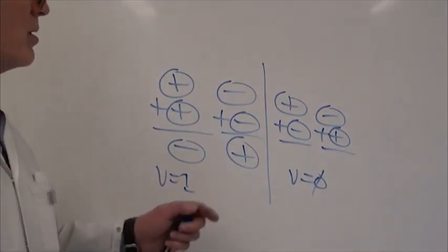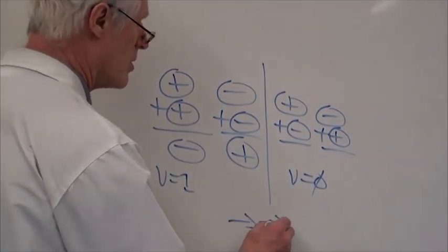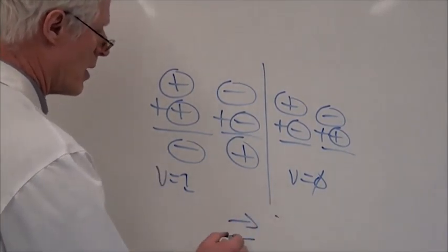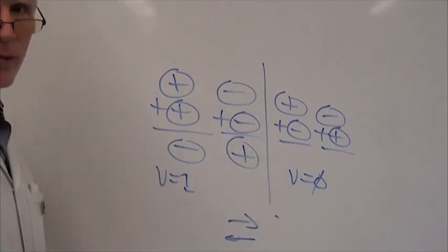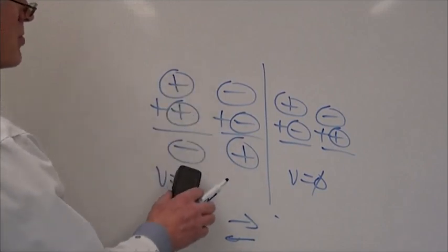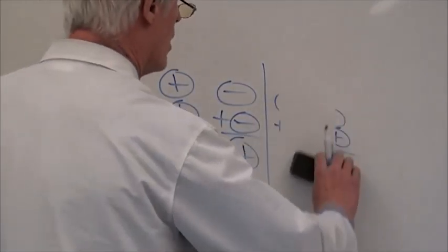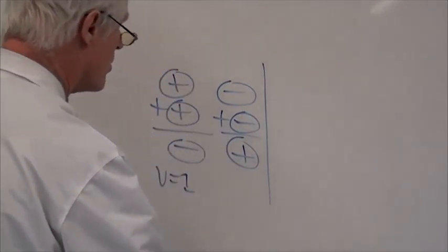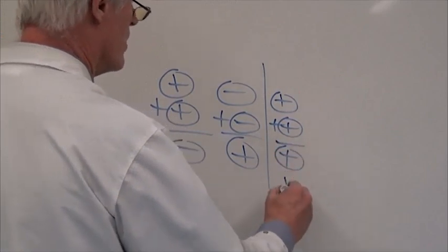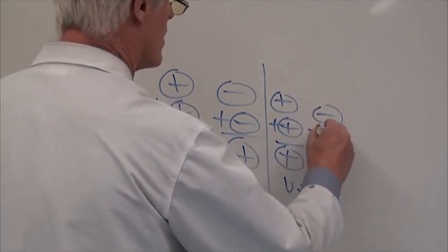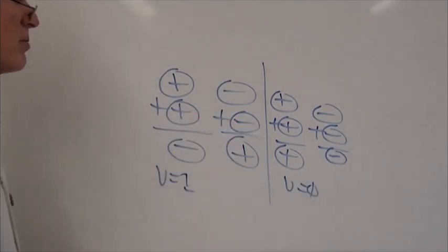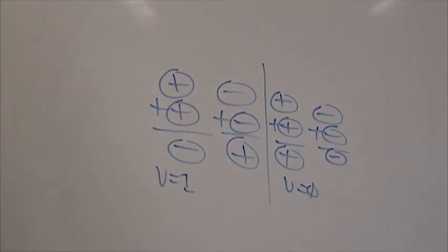And why is that? Because if you add a positive, you can go over this end, but if you add a positive to a negative, you're in the middle somewhere. Okay? And the other thing is, so these are V equals 1. If you add two positives, get a negative, add two negatives, get a positive. Also, if you happen to do the normal stuff and say I've added a positive plus a positive and I got a positive, V is 0. If I add a negative and get a negative, V is 0, because that's what you expect. When you get something you don't expect, V is 1, which is our signed overflow.